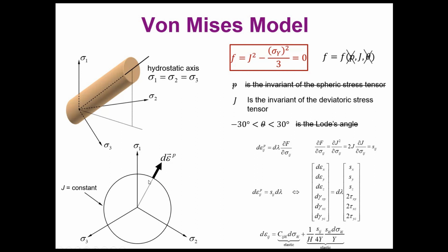In this case, I'm showing it here when the surface is expanding. So we are going to need to know the direction depending on the point on the surface we are, and the quantity of this plastic deformation when the hardening is being produced, as we saw in the experimental test in the steel, for example.